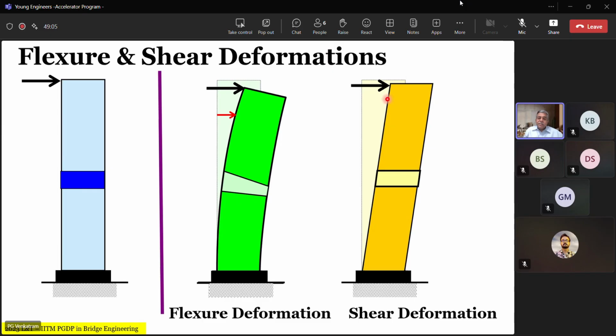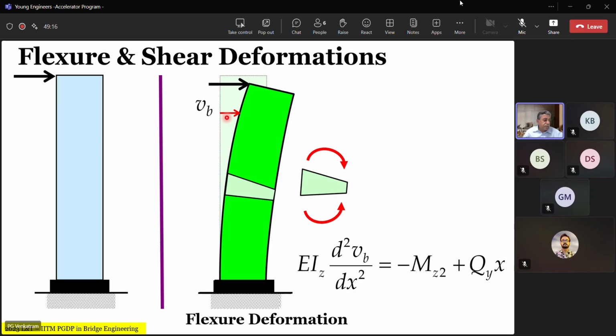And therefore, for a simple cantilever, if we have to understand the stiffness, what's the stiffness for a simple cantilever? Okay, I'll grant you that way. It is 3EI/L. I said simple cantilever, but you talked about a general member in flexure, EI/L.